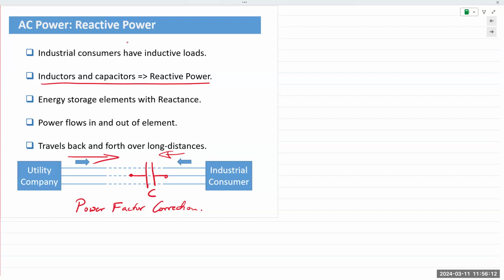If you have a large industrial customer that is setting up a new factory, or perhaps the power goes out, and now all of the machines need to come online, the customer has to work with the utility company to do staggered turn-ons. You cannot just flip all of the switches on all at once.